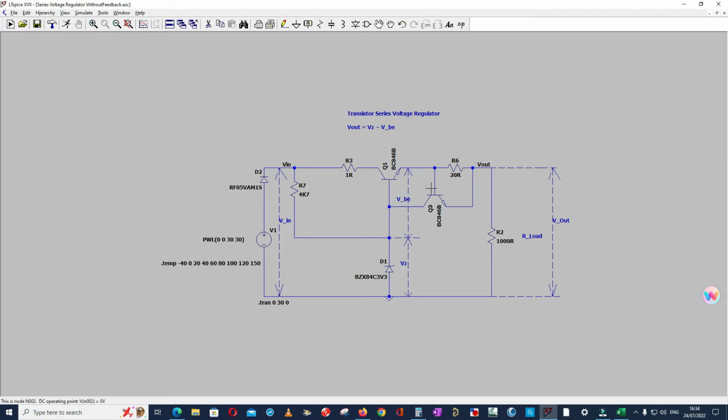For example, I have a resistance of R6 of 20 ohm, which means that when around 30 to 40 milliampere flows through this R6, the voltage drop across R6, which is the base emitter of Q3, is around 0.6 to 0.8 volt, and that is enough to activate Q3.